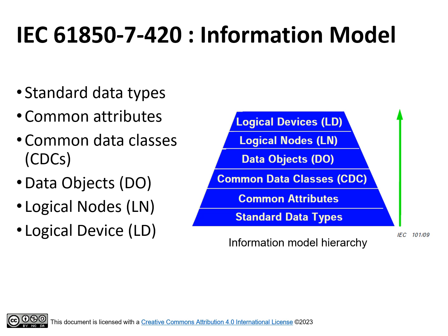Number 6, logical devices, LD. The service model composed of relevant logical nodes for providing the information needed for a particular device. Example of the logical device: a circuit breaker device could be comprised of the logical nodes, circuit breaker node, XCBR, and switch controller node, CSW.